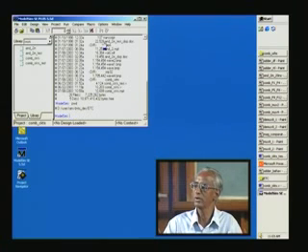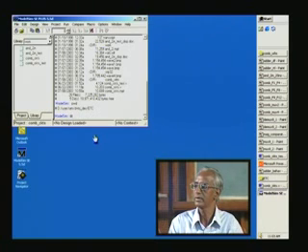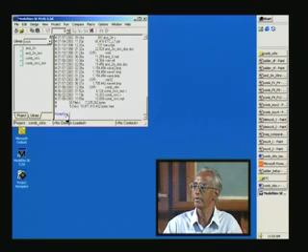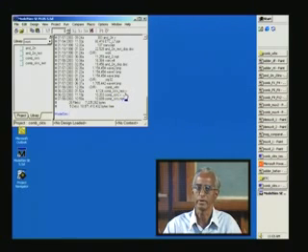If you want to view all the files in this particular directory, just type dir at the ModelSim prompt here. So it lists all of these. It may be difficult for you to read, so I'll read them out. We have combinational_circuits.v, and combinational_circuits_test.v. This is what we have already seen earlier, and we'll be seeing again, and this is what we are going to simulate. Before we simulate, we have to do the compilation that we have already seen in the flowchart we considered earlier.